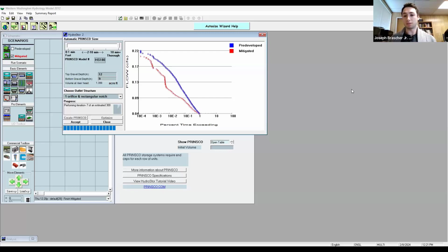Let me go down here. Someone asked, does the quick chamber population values just use default values? Do they scale based on the size of the area you're trying to model? No, they do not. It's the same values for everything. So quick chamber has nothing to do with your project. Just want to make sure that's clear. It's just going to quickly populate the values. No design criteria are taken into account at all.